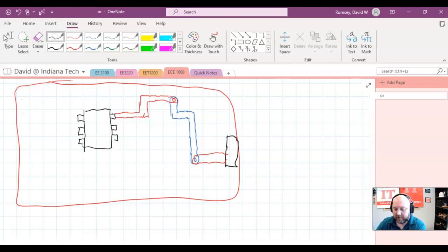If you're talking about manufacturing them in the lab currently, we have to make them big enough to be able to either solder a piece of wire through it so that you can actually get a physical connection from the top to the bottom. If you just drill a hole through here, the top and bottom are not going to be connected, because these boards are fiberglass, and then there's a layer of copper on the top and bottom. So if you drill a hole, there's no connection between the top and the bottom. The only way to do it is we have a grommet system, literally little grommets that you put into each hole, and then you punch them and flatten them out. That can make a connection from your top and your bottom, or you stick a piece of wire through it and solder it on the top and the bottom.